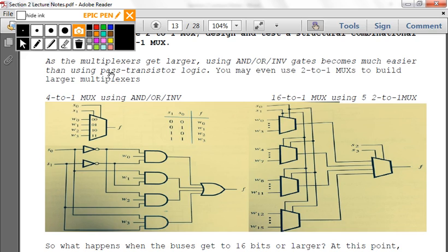I have two 32-bit input values that I want to multiplex, and I want to choose one of these two. Here's an example: if we are doing an R-type instruction, and we have a previous instruction where we've done a load word, there's still this existing calculation that we've done, so we want to pick between those. For now, just press the I-believe button. At some point, that'll all make sense. But we have two values that we absolutely must choose between.